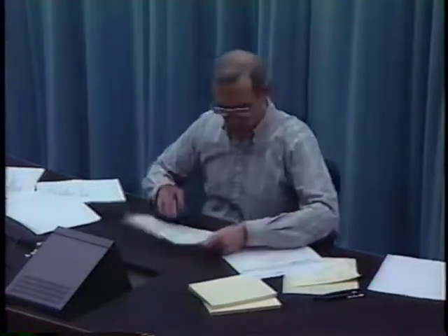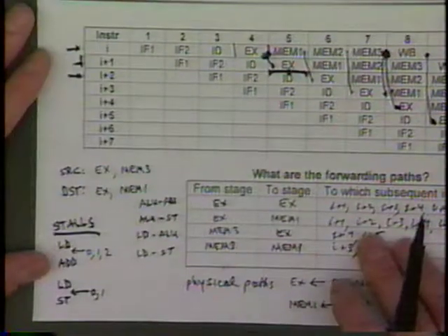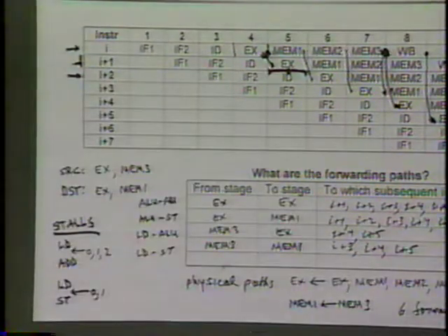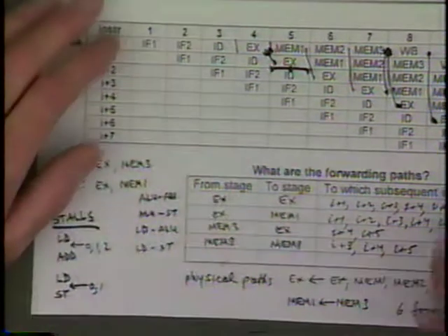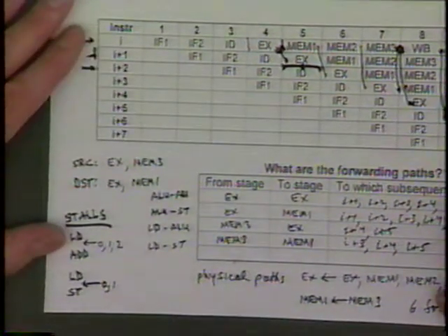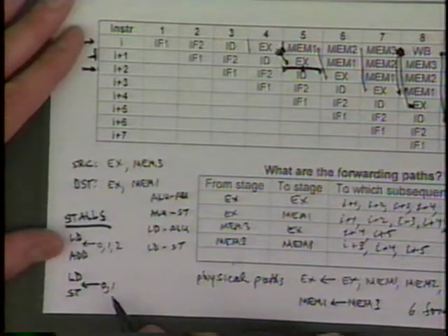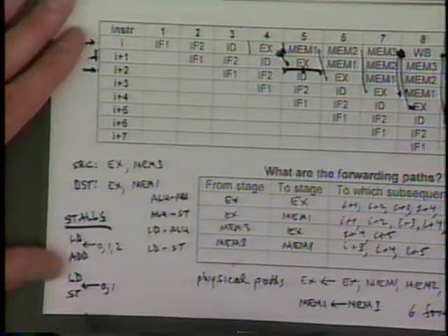So then the load delay should actually be 1, 2, or 3 cycles, not just 2 or 3, depending on how many instructions you have between the load and the add or the load and the store. Do I have a mistake here? Help me, Lance. Do I have this right? Well, you could have a load and then some unrelated instruction between there, and then the store, and in that case, you'd have 1 load delay.